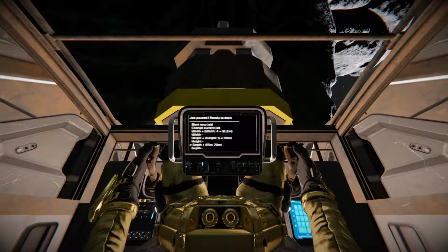When we move down and we see depth, we'll just quickly set this one down. So depth on default mode, this is how deep it will go. Once it reaches this depth, it will consider that hole done, and it will reverse out and move on to the next one. You can set this as high or as low as you need it to, or we can use depth mode. So in this one we have default, which is just your static depth, or we can go auto.